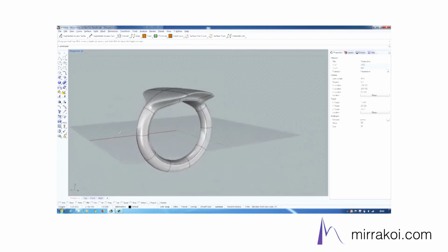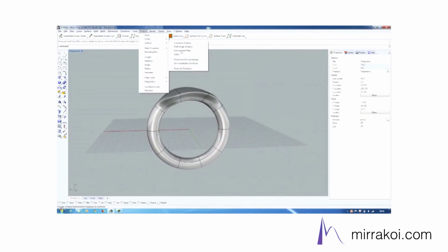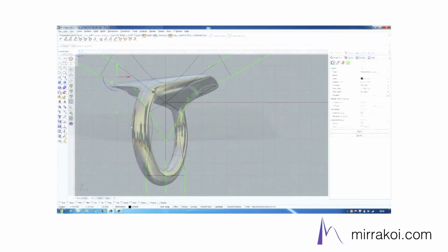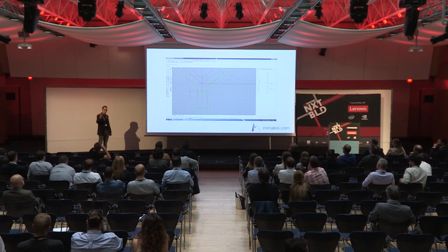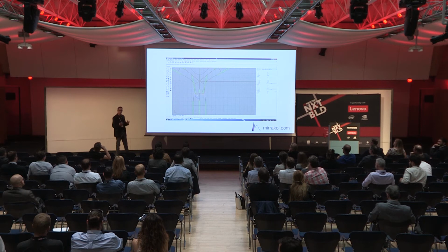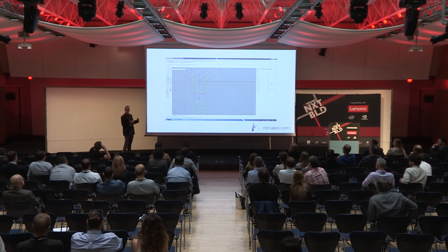The same thing you can do with curvatures or tangent planes, and you can really adjust these quantities in a decoupled manner. So if you spend some time to adjust some curvature value, this will stay there. Then you can spend some time to adjust the tangent value. You can spend some other time to adjust the surface point. Everything's decoupled. So this gives you some kind of new freedom of operation when you do 3D CAD. This gives you new ways of doing surfacing or coming up with surface shapes that you cannot do if you just have the very classical NURBS-based control point structure.